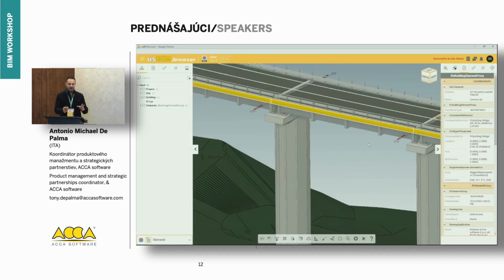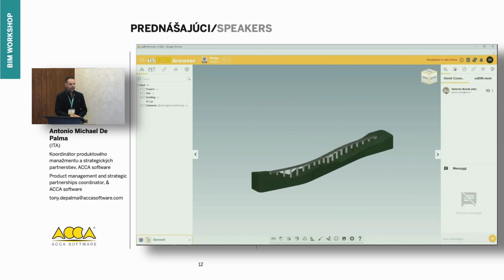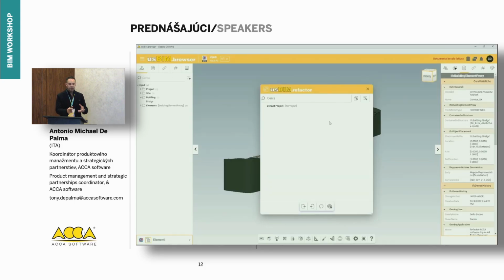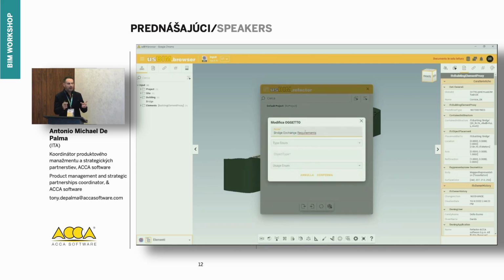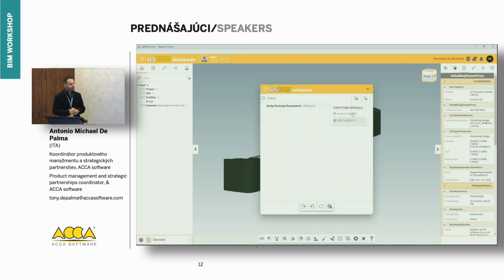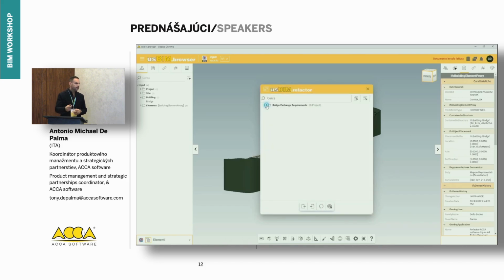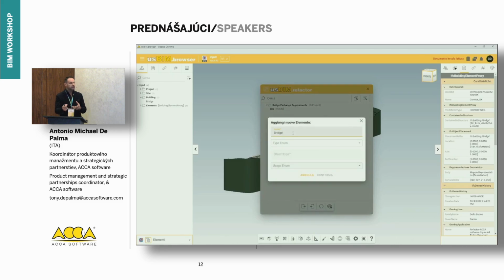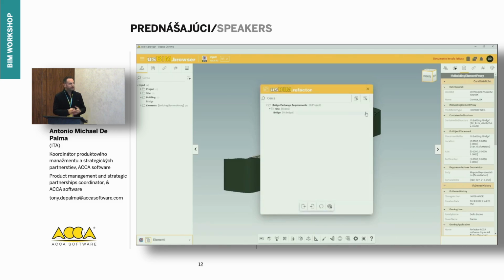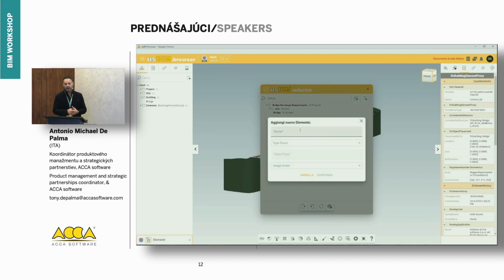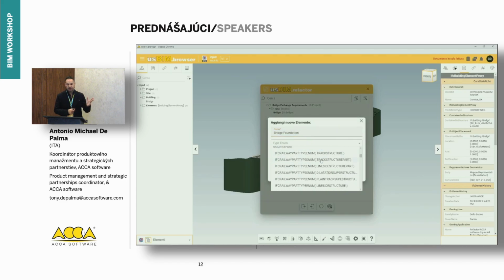So in this particular case, we're looking at an IFC 2.3 version of this viaduct, okay? And the feature here is that we can reorganize the spatial structure of the geometry, assigning new attributes, new property sets, okay, and aligning it therefore to the new structure of an IFC4, typical of an MEP system or of an infrastructure asset such as this viaduct.